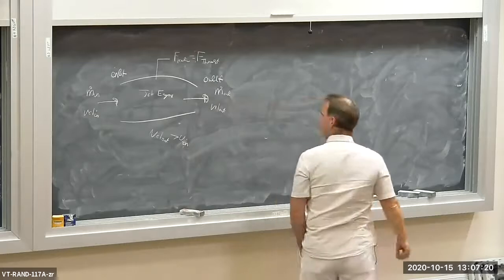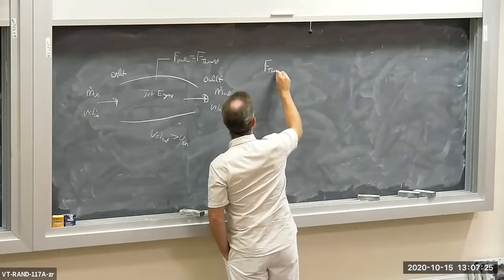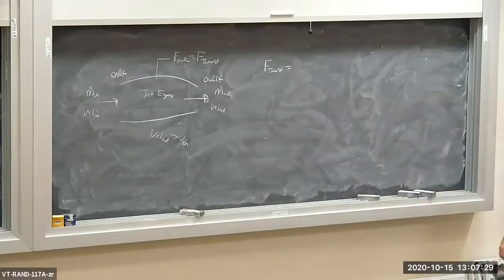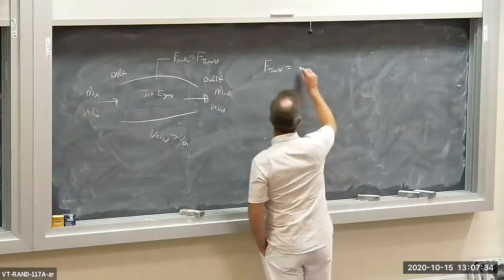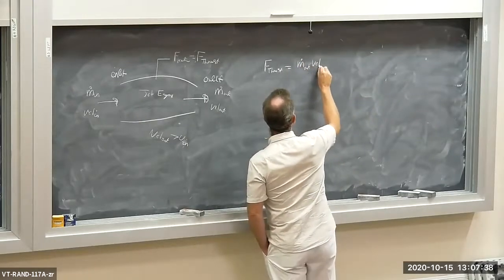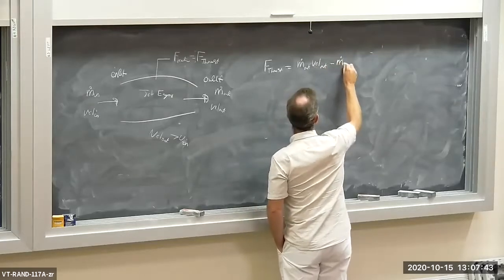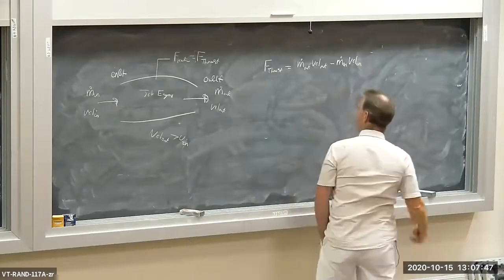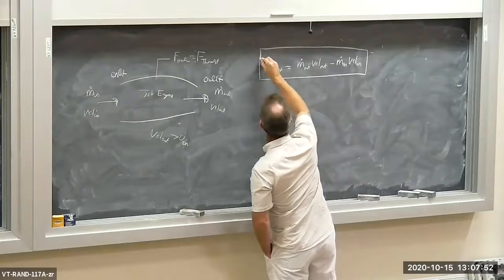And the equation for thrust produced by the jet engine, so F thrust is equal to the change in momentum flux in the horizontal direction. So we have m dot out, velocity out, minus m dot in, velocity in. So here's your expression for the thrust produced by the jet engine.